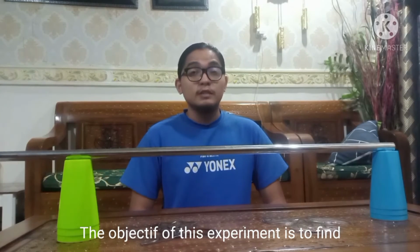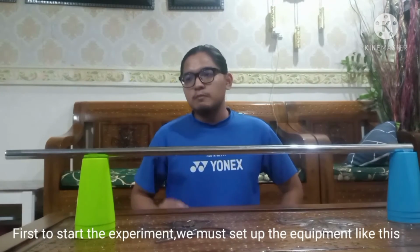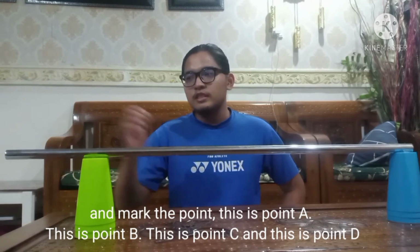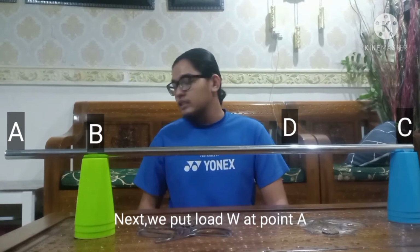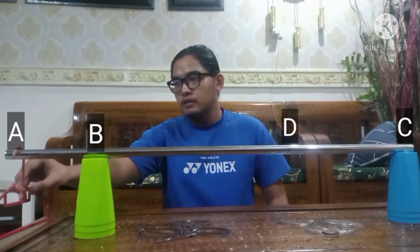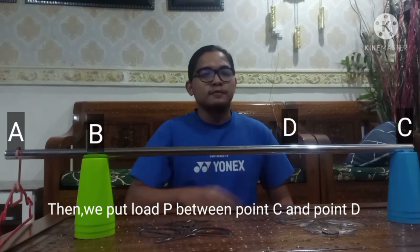The objective of this experiment is to find the point of contraflexure where the bending moment is 0 first. To start the experiment, we must set up the equipment like this and mark the points. This is point A, this is point B, this is point C, and this is point D. Okay, next we put the load W at point A. Then we put the load P between point C and point D.